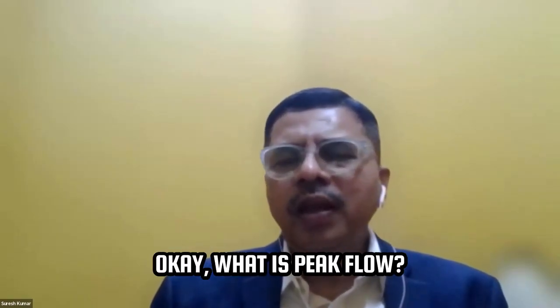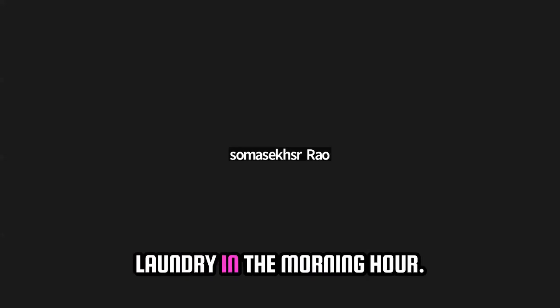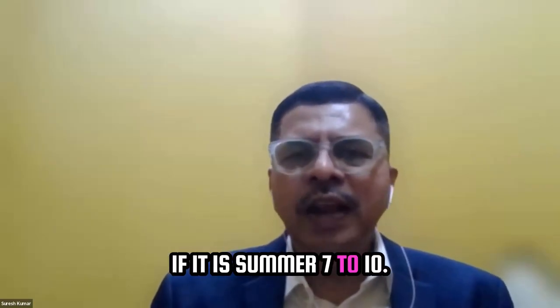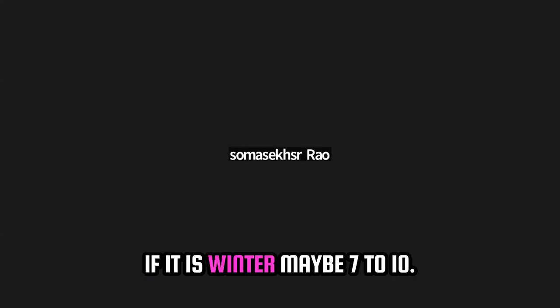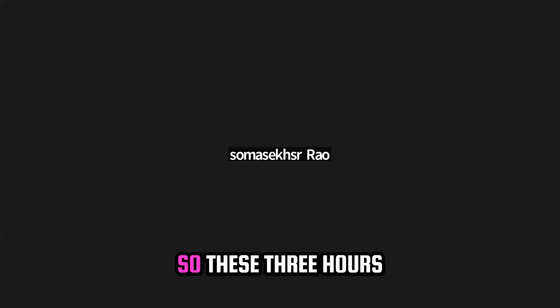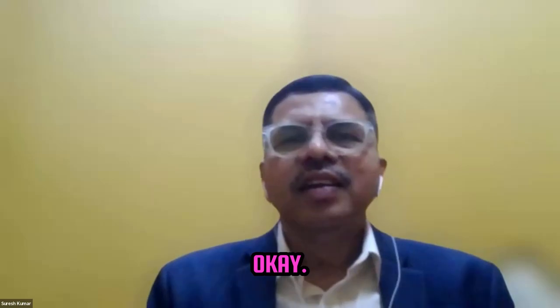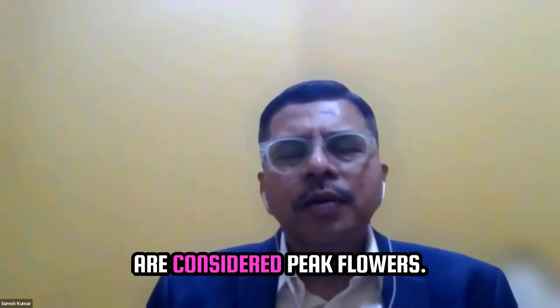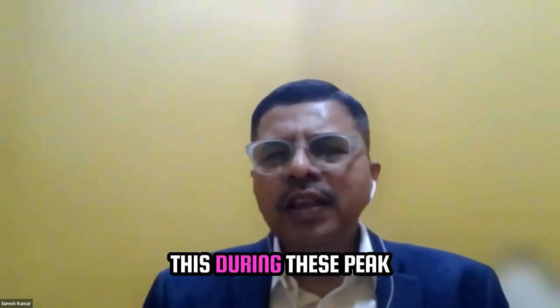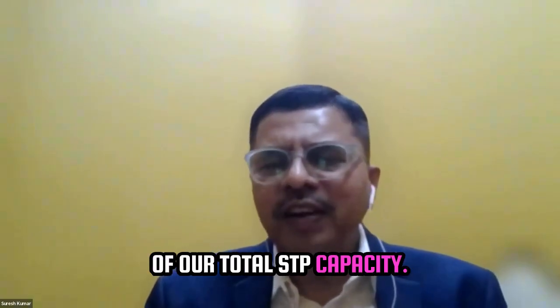What is peak flow? Everybody is using the toilets, bathrooms, kitchens in the morning hours, laundry in the morning hours. If it is winter, maybe 7 to 10. If it is summer, 6 to 9. So these 3 hours are considered peak flow hours. During these peak flow hours, we are going to generate roughly 40% of our total STP capacity.